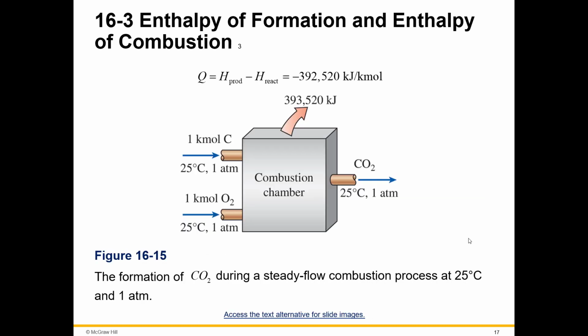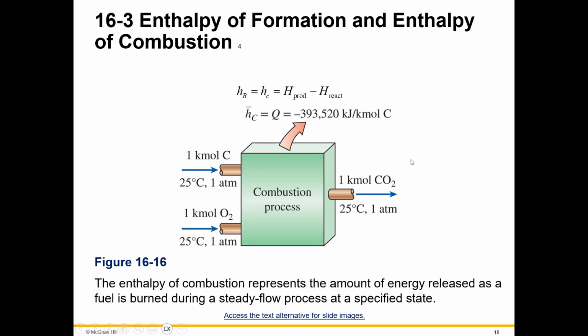And then we can look at, well, what is that enthalpy of combustion? This is continuing on with a schematic showing the formation of CO2 during a steady flow combustion process at 25 degrees Celsius and 1 atmospheric pressure. So here, the enthalpy of combustion represents the amount of energy released as a fuel is burned during a steady flow process at a specified state.